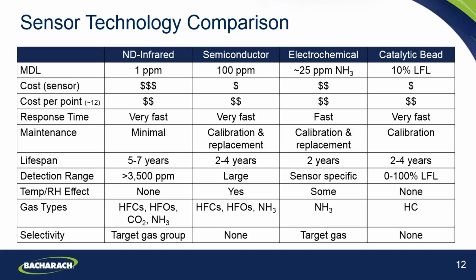The response times on the sensors are all good for the applications, with fast response. Maintenance does vary depending on the different sensor types. Again, the infrared sensor leading the pack there with minimal maintenance required. The other sensors are all more requiring of calibration, and semiconductor and electrochemical sensors also have a shorter lifespan, requiring replacement every 2 years or so. Sometimes a bit longer with a semiconductor sensor. You might get up to 4 years from one of those.